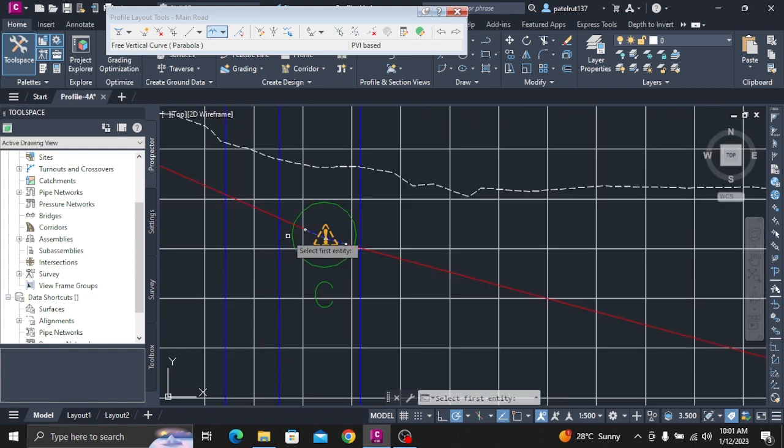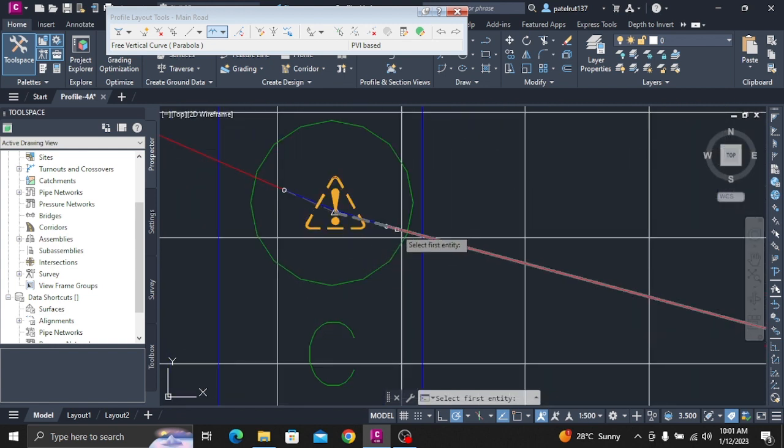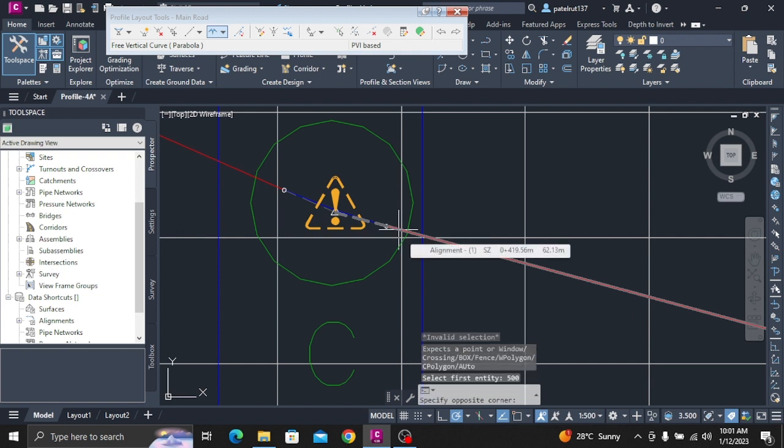In the Specify Profile Display Options table, select the Draw checkbox for the following profiles, e.g. Left Offset. EOP Left. In the Select Stacked view to specify options for list, select Bottom view. In the Specify Profile Display Options table, select the Draw checkbox for the following profiles, e.g. Right Offset. EOP Right. Click Next.